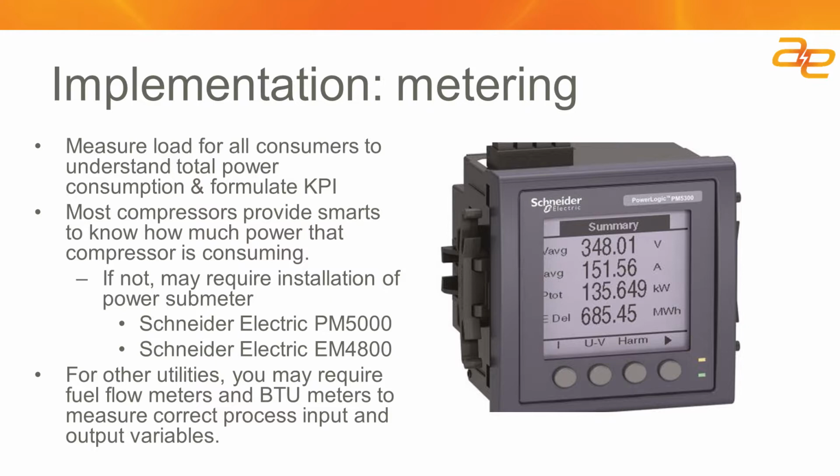So it's important to make sure that when you put in a control sequence that requires the measurement of input and output parameters, that instrument is also calibrated on a regular basis.